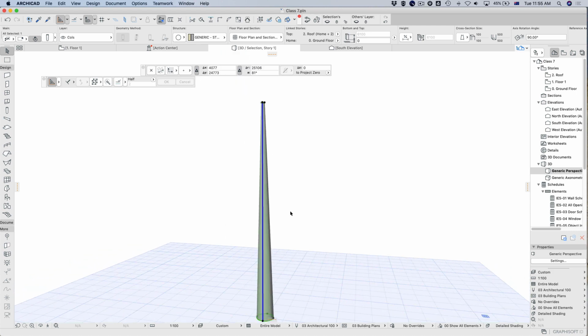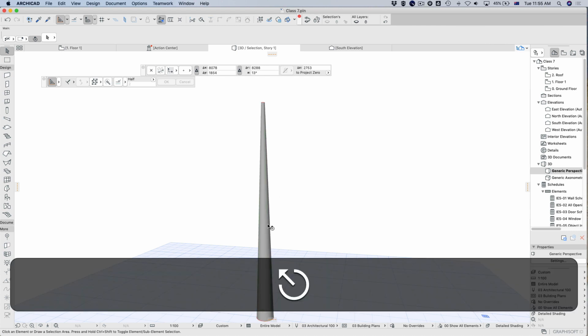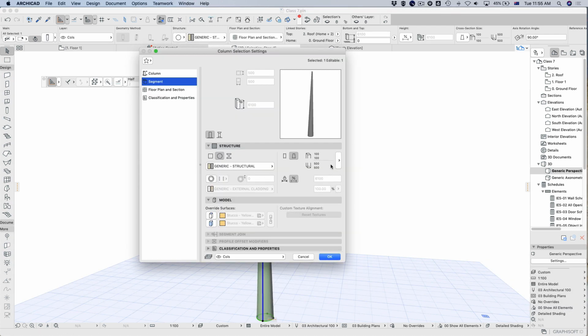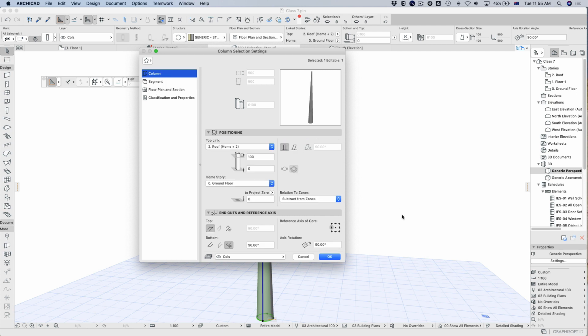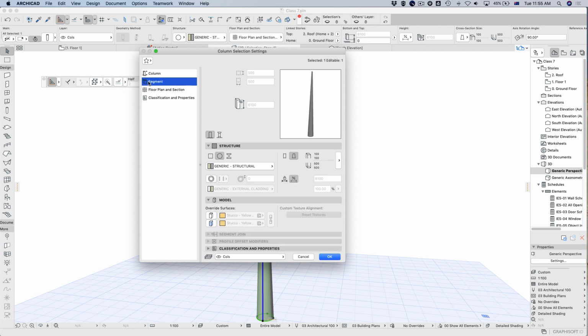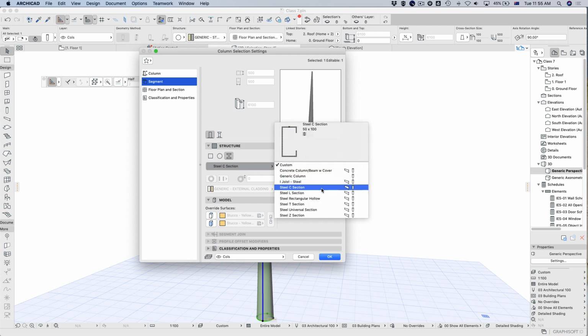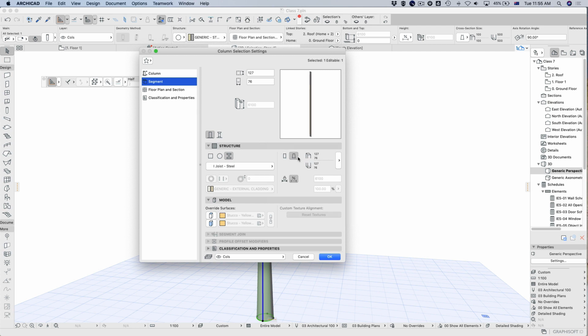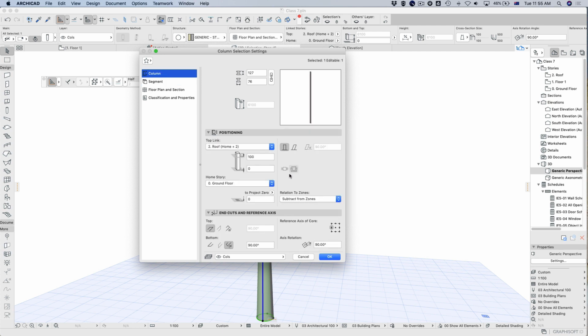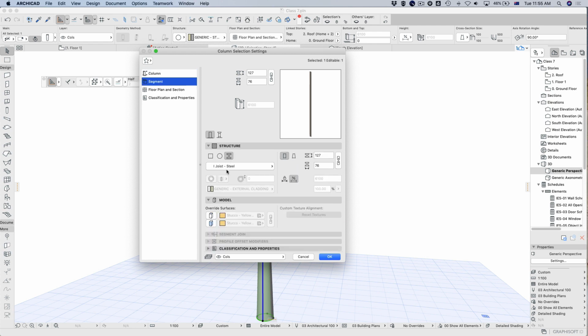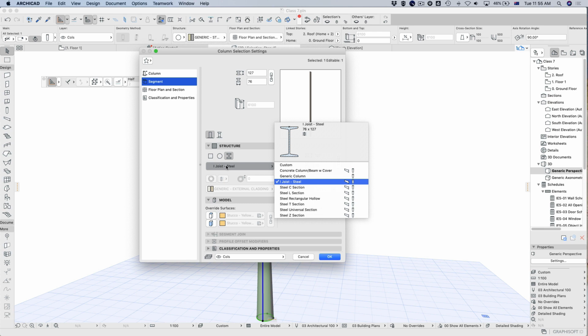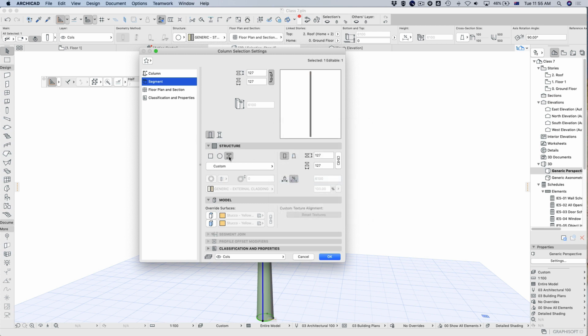Okay, so there are a few settings. Remember the beams on an angle, the cladding will disappear, and also the tapering will make it disappear as well. And you can actually tell because when you go back into here, you can see that it's greyed out. So if it's greyed out, just check to see that you haven't got that on. I think you can still do, so I did an I-beam. Yeah, see, the I-beam won't let you either. So it's not always an I-beam, it's your profiled columns. That's why I said I will come and visit this in a second.